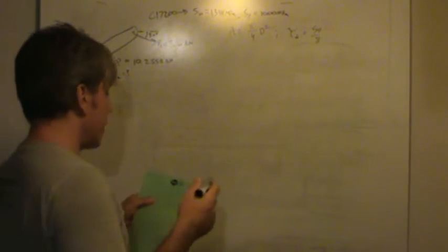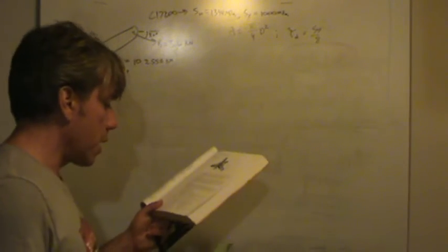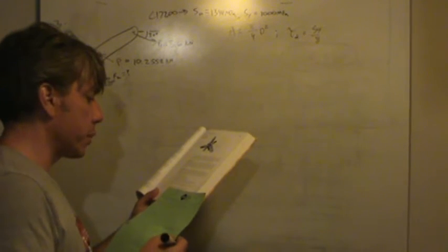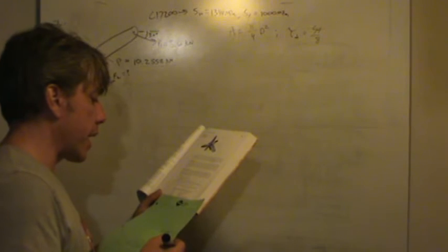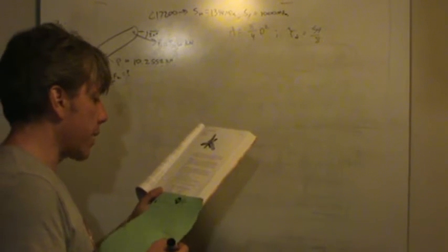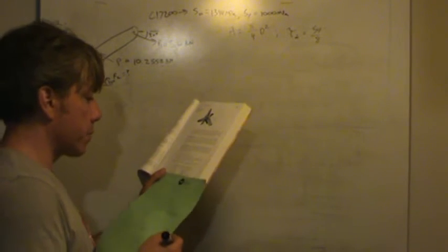Well, there's some more information in your book, I think on the same page. Yeah, here we are. At the bottom of page 159 in table 3-9, it says estimates for the ultimate strength in shear. And it says for malleable iron and copper alloy. So this is a copper alloy because it was a beryllium copper and it's hard.